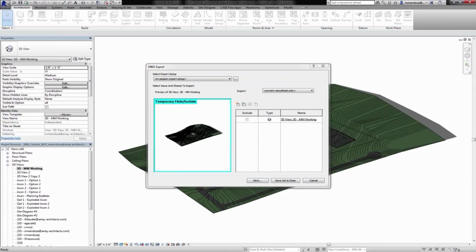And meanwhile, working from a survey, we were basically able to develop the complex geometry of the site. The last thing I'm going to do here is spend 5 minutes or so and take you through this workflow of how we get accurate topography from a survey that's built in Revit, using pad sites and points on the topographical surfaces in Revit, not a conceptual mass but the actual site tools in Revit, and getting that back into FormIt and combining it with the building.